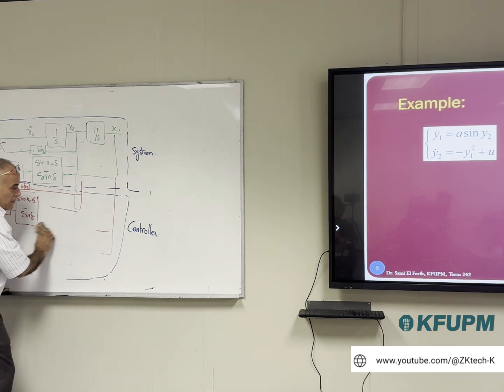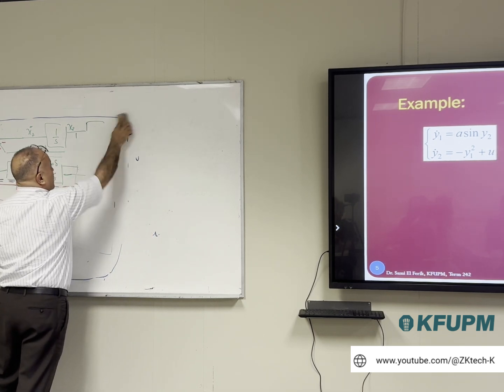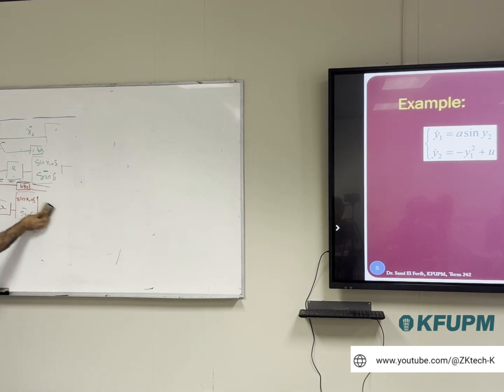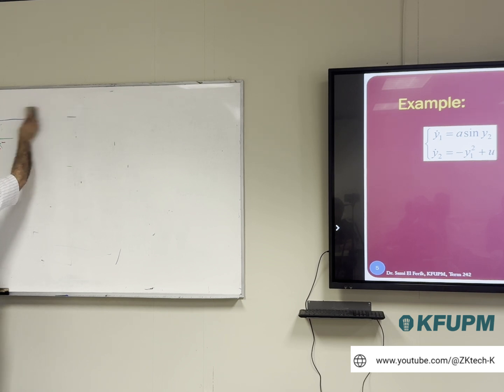Otherwise, you will have oscillations, because the two controllers, one is trying to do something and the other one has not settled yet. You will have issues in terms of control. So this is from a practical point of view.